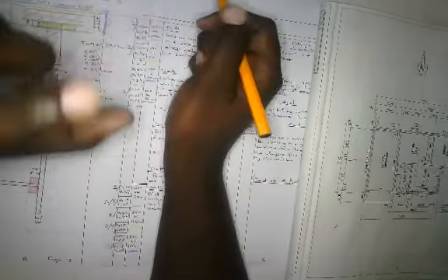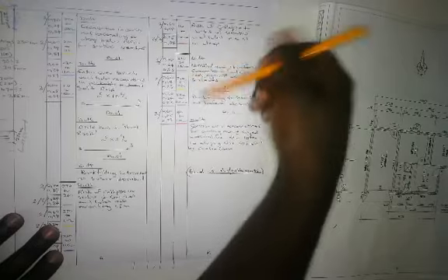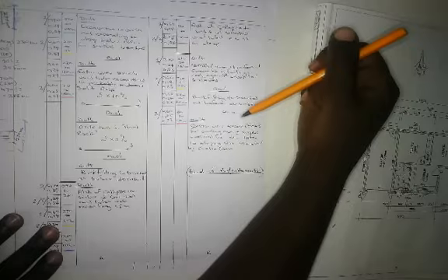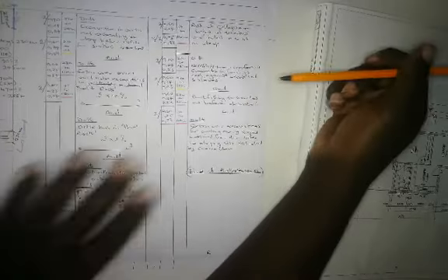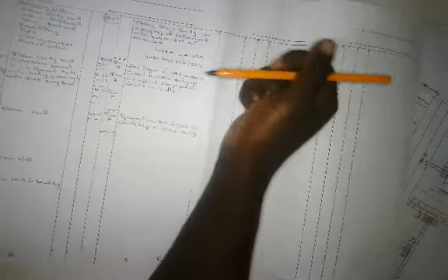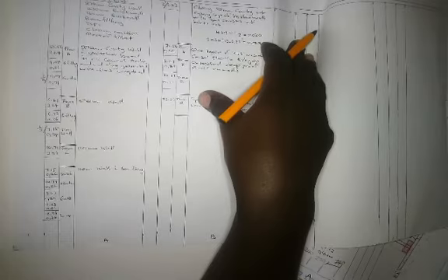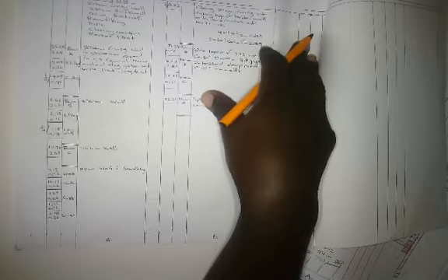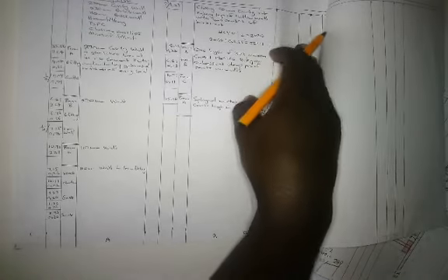So the dimensions that we are using here in the excavations, you're going to transfer them to your 10 MPa. Difference, you're going to say 0.7 by 0.24, which is from here to here, by the thickness of your footing, which is 230. You're going to deduct that. You will do that for the other wall adjustments also. So that will be the end of adjustments, guys.